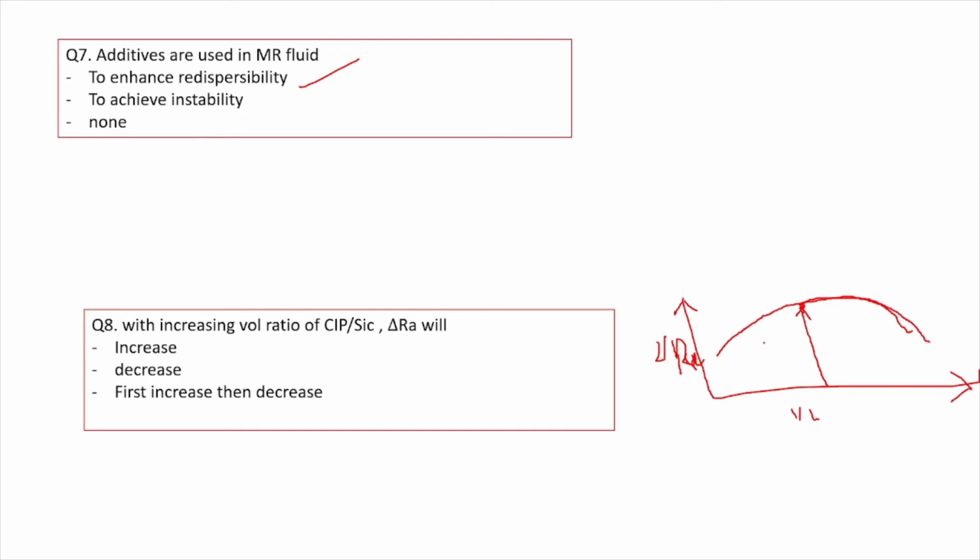Why? Because at that time the number of abrasive particles will be less, and the bonding strength will be very low to even polish the material. Polishing will not be possible in that range, due to weak abrasive particles or fewer abrasive particles.